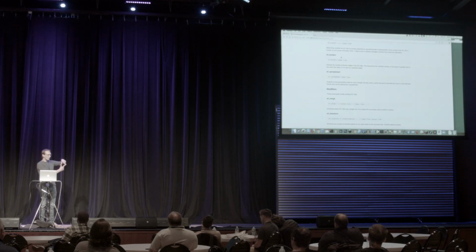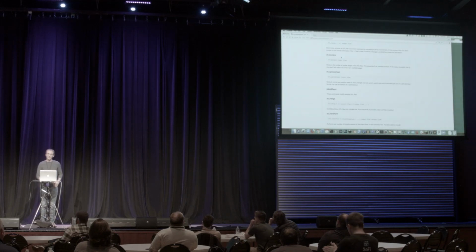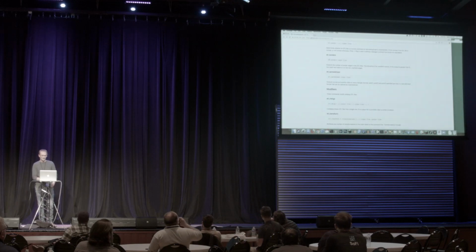But if you have a hole, these edges have no shared triangle, so only one triangle has this edge. So they're called border edges. If you count the border edges in your model and that's greater than 0, it's not a watertight model. So that can be helpful for debugging issues like that.